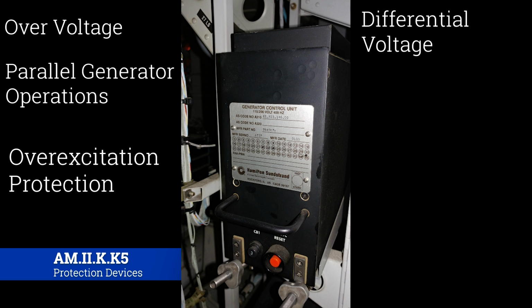Okay, so differential voltage is another really interesting one. What will happen is the GCU will look and see, hey, what's the voltage inside of the system right now? And it should be about the voltage that generator wants to produce. Then it looks at the voltage that is actually coming off of the generator and says, are these two voltages within a certain, really tight tolerance? Basically, are they the same? If they are, then it closes the tiebreaker, and boom, off it goes. But if it's not, then it won't let the tiebreaker actually close and connect it to the rest of the system.